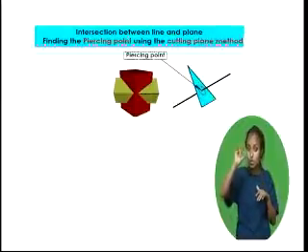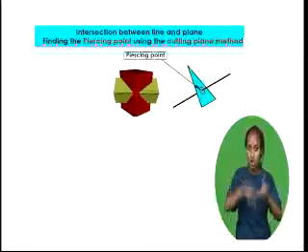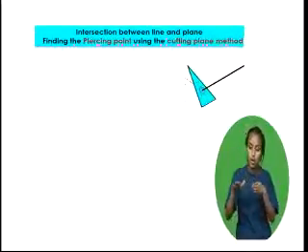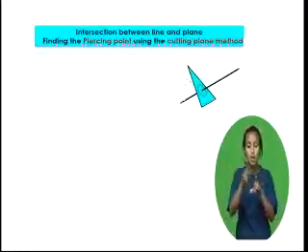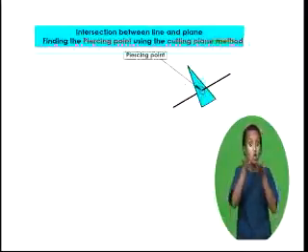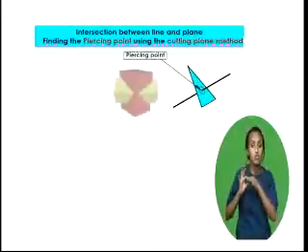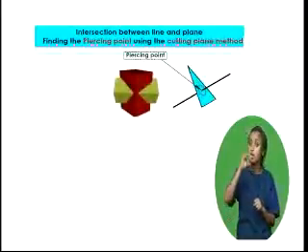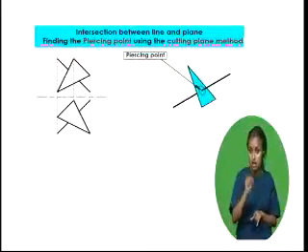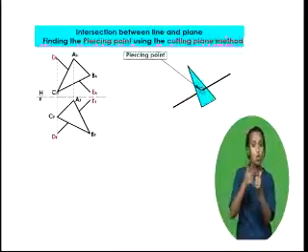On orthographic views, the piercing point of a line and a plane can be found either by cutting plane method or edge view method. When a line pierces a given oblique plane and an edge view is not given, a cutting plane may be used to establish a line of intersection that will contain the piercing point. To find the piercing point of line RS with plane ABC by cutting plane method, follow the following steps.